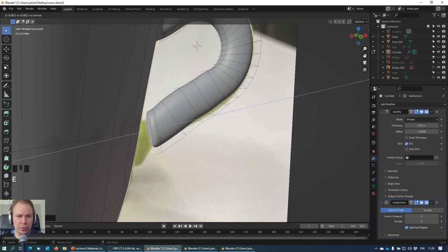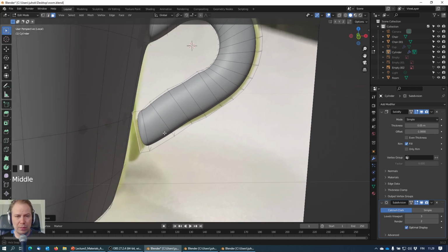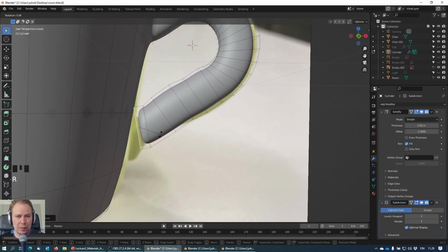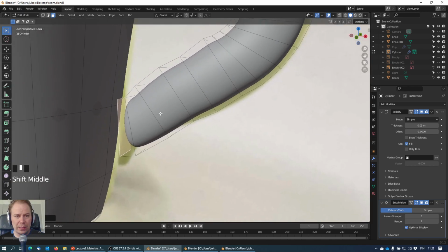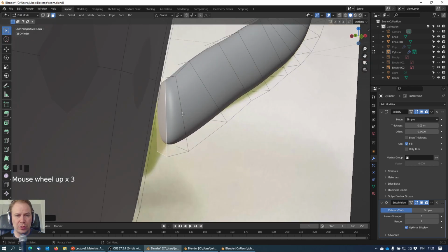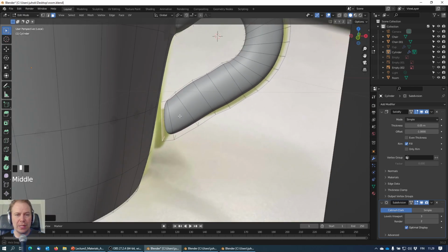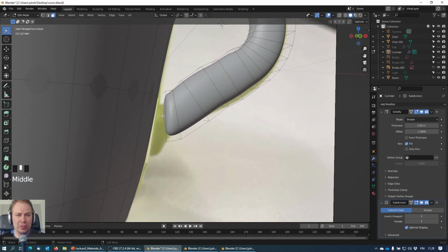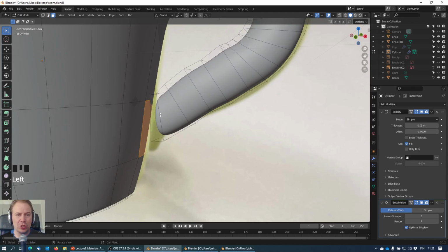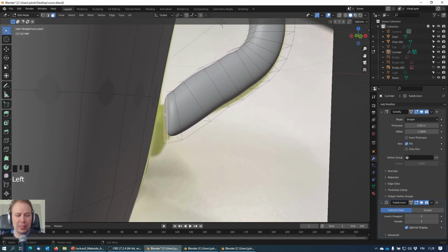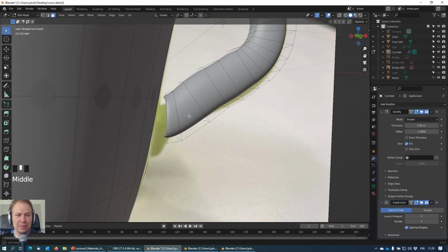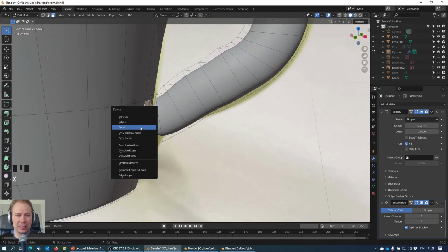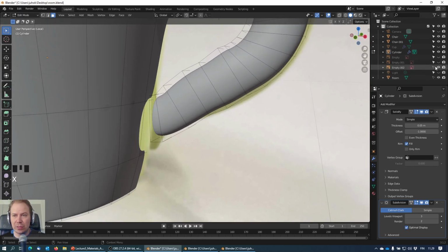And then one more step maybe here. Okay, and then rotating it a little bit along the y-axis. All right, and what we can do here is we need to join these areas together. So first you need to get rid of these faces so you can join these together. Just click X and then face, and X and then face, to get rid of this.